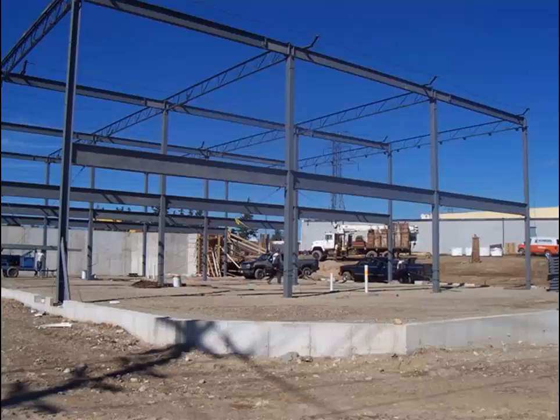Here's another photograph of a steel frame structure. One thing that I think is obvious when you look at this is the aspect ratio between the beams and the columns. And it is indeed typical to see the beams have a greater depth than the columns. This aspect ratio may be a little bit skewed towards the size of the beams, but it is common for the depth of the beams to be somewhere on the order of a W21, W24, and the depth of the columns to be more on the order of a W12 or a W14. So that is somewhat typical.